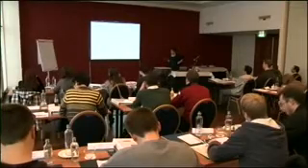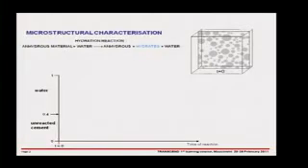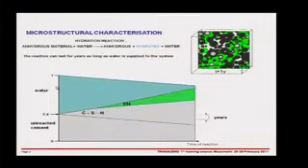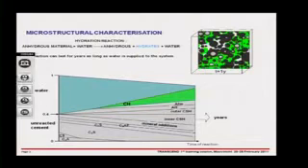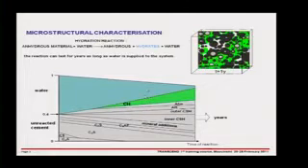So the basic idea, I think, as you've already seen, we have a material reacting. At the start, we have unreacted cement, and we have water. And over time, we get the evolution of all these different phases. And depending on the level of complexity we want to have, we can be concerned with all the different cement minerals, all the different CSHs, calcium hydroxide, etc., etc. And what we want to do in terms of characterization is work out how much of all these phases we've got, what their compositions are, what their arrangements are, etc.